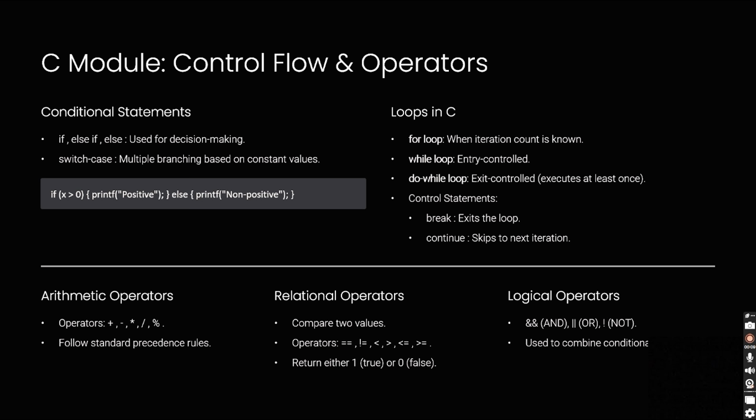We used if else and switch case statements to handle different conditions like checking switch states, selecting washing programs, or activating the buzzers. Switch case was especially used for program selection. Control flow is the backbone of our state machine logic. The while loop forms the super loop in our embedded program. We used for loops for delay generation or state counters, and control statements like break or continue to exit loops or skip certain iterations. Each loop is carefully structured to ensure real-time performance.